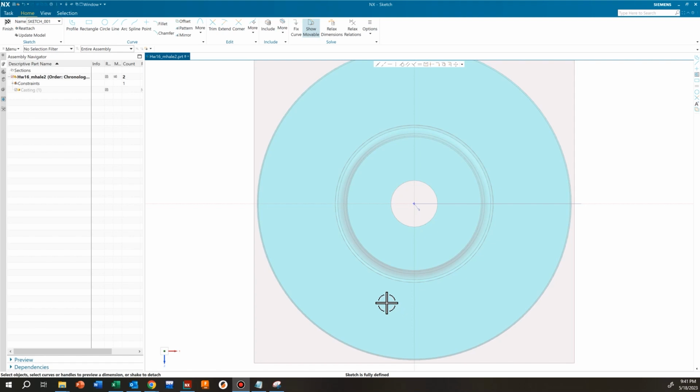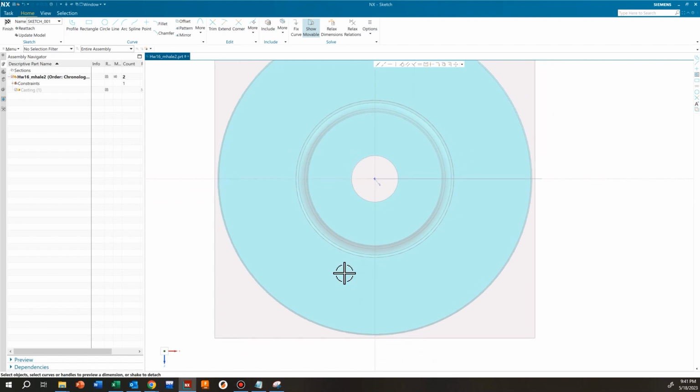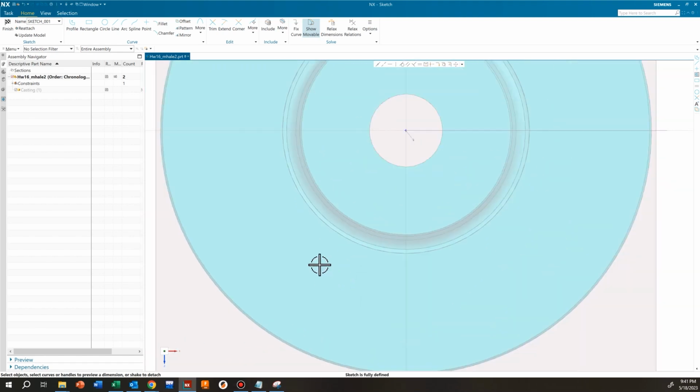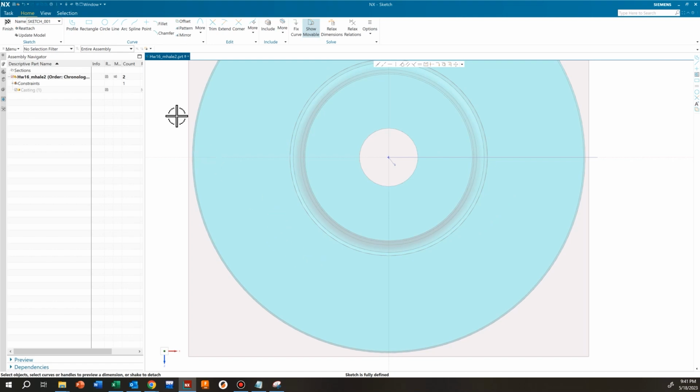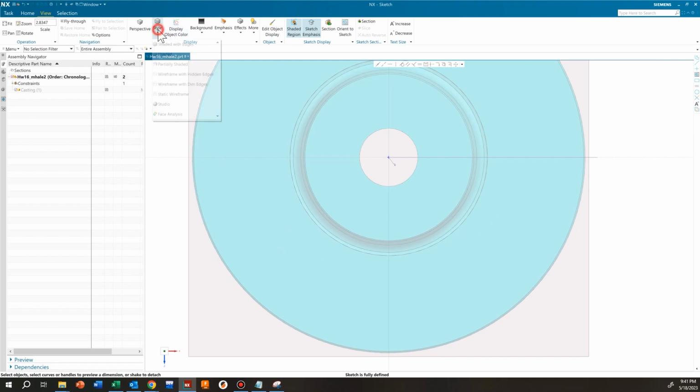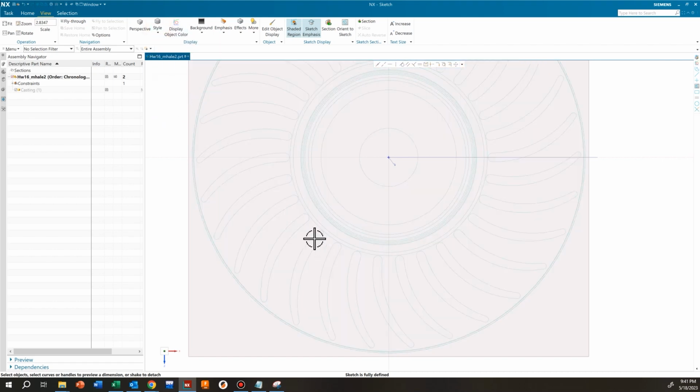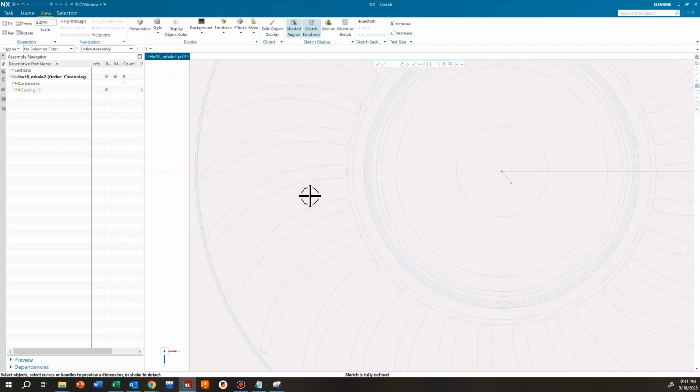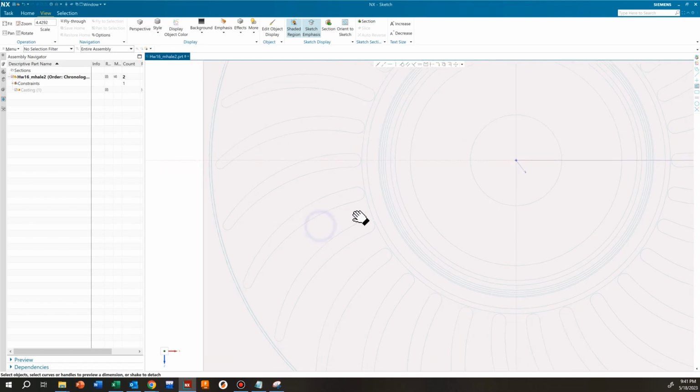And we need to position our holes between the internal fins. We can't really see them right now. So what I'm going to do is go to View and change into Static Wireframe. Now we can see those internal fins. So our holes need to be between these fins.